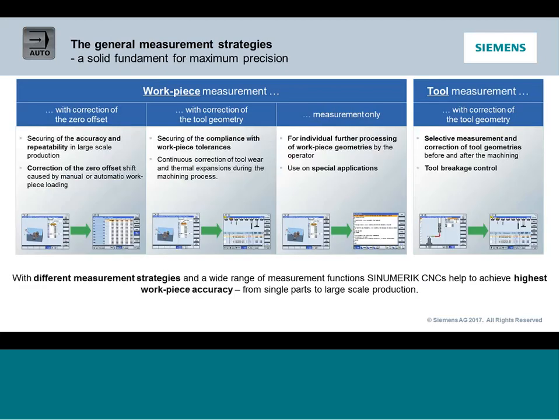So what can we do with them in auto? What are the most typical functions that people are going to use these for? Certainly work offset correction. So whether I'm afraid that the part gets loaded slightly skewed, I want to come down and align to it. You can use it for adjusting tool geometry. Just because you're measuring the part doesn't mean you have to write the correction into the work offset. We could write it into the tool offset. Maybe I'm coming down in a pocket, I'm expecting that end mill had machined the pocket a half inch deep, and it's a couple thou shy of that. We can write that correction to a tool offset as well as shift the work offset. Or you can use it for measuring functions.